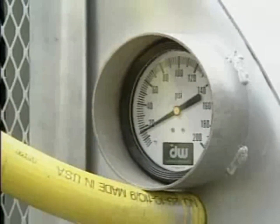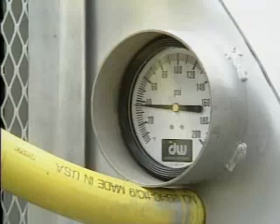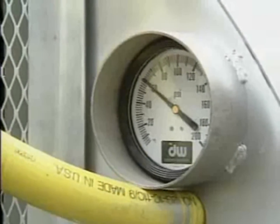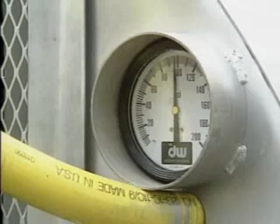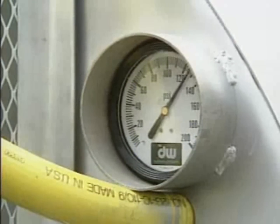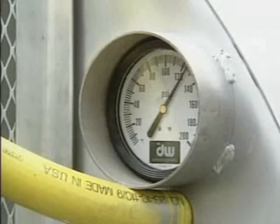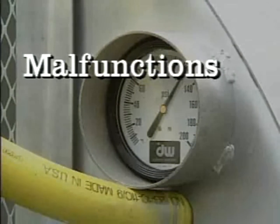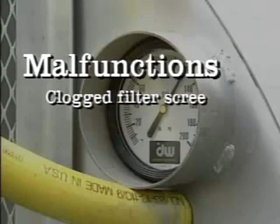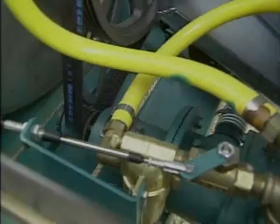Pressure gauges monitor the system's pressure. They should indicate the pressure at the sprayer manifold. The spray system is usually set to operate at a certain pressure to assure a particular output of the system, and the pressure gauge indicates any change in that preset pressure. A change in the preset pressure alerts the operator that the system is malfunctioning. Malfunctions may be caused by clogged filter screens, changes in pump output, or regulator problems.